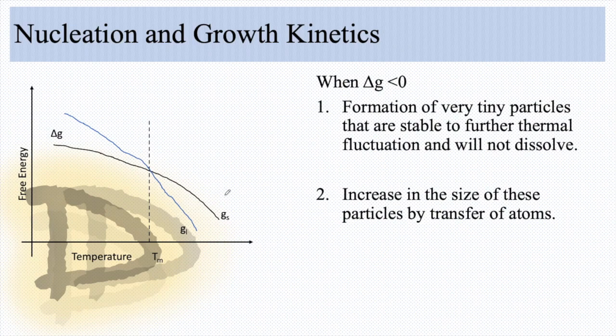As given by the graph, in which free energy is along the y direction and temperature along the x direction, for the liquid and solid, the difference del G can become negative when the temperature is below the melting point. Liquid can spontaneously transform to solid.